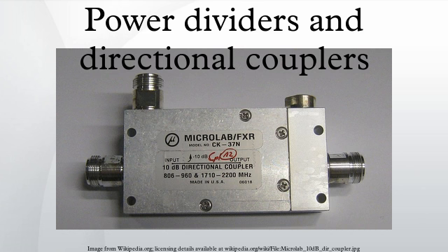The Wilkinson power divider solves the matching problem of the simple T-junction. It has low VSWR at all ports and high isolation between output ports. The input and output impedances at each port are designed to be equal to the characteristic impedance of the microwave system. This is achieved by making the line impedance √2 times the system impedance. For a 50 Ω system, the Wilkinson lines are approximately 70 Ω.